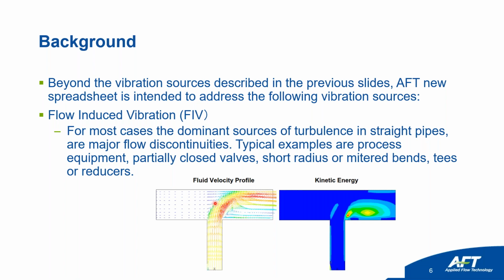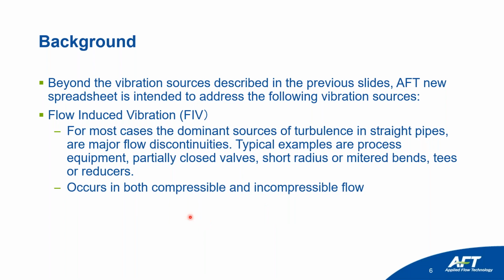This perturbs the flow that comes in the main pipe and creates a kinetic energy that has a potential to create vibration problems downstream of the T. This flow-induced vibration can occur in both compressible and incompressible flow.